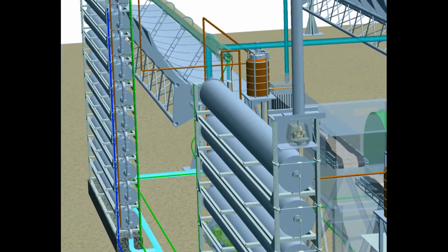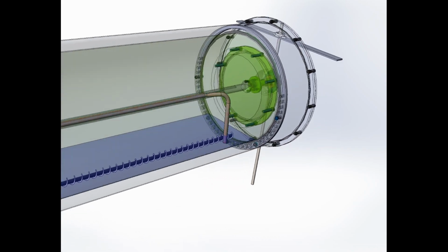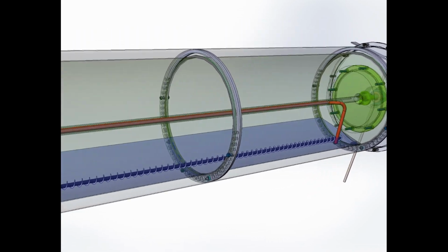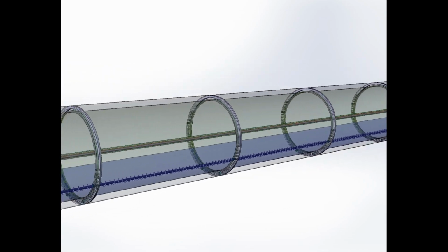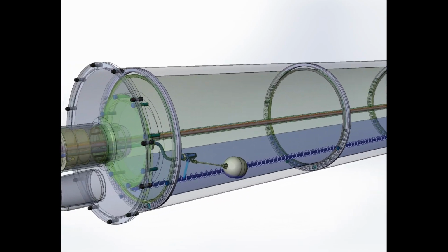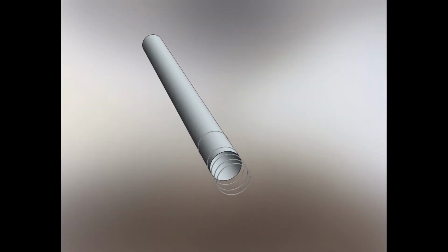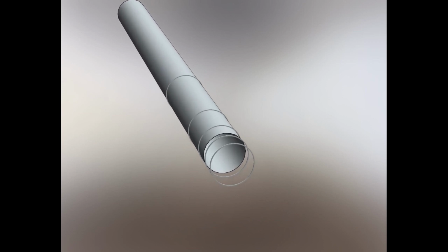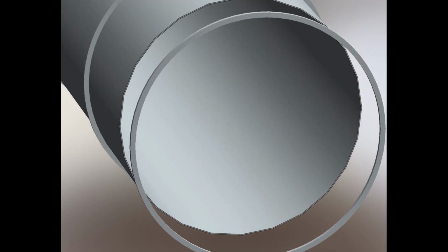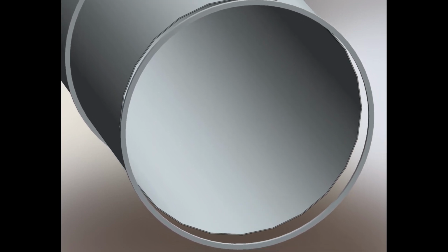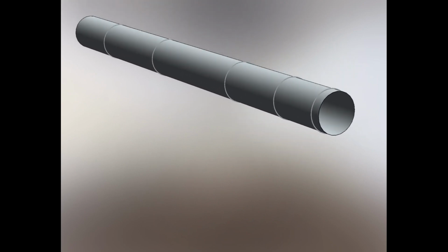Let us consider in detail the design of a separate module of a 10-stage evaporation plant, which, in regions with maximum insolation, ensures the production of fresh water on average about 10 cubic meters per day, about 1 cubic meter per day for each module. The main structural element is a rotating drum made of thin-walled large-diameter pipe, partially filled with liquid. For the example under consideration, the internal diameter of the thin-walled pipe is 480 mm, the wall thickness is 2.5 mm, and the pipe length is 6 meters.